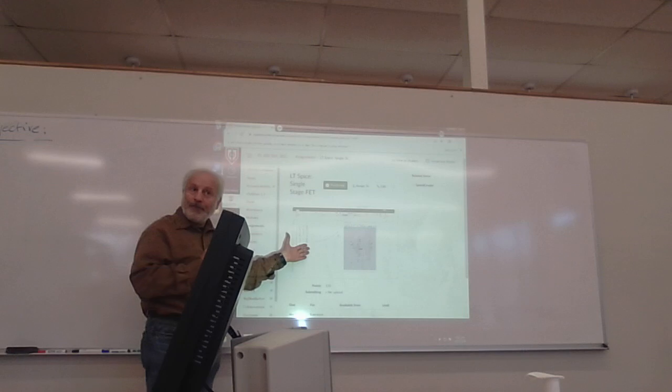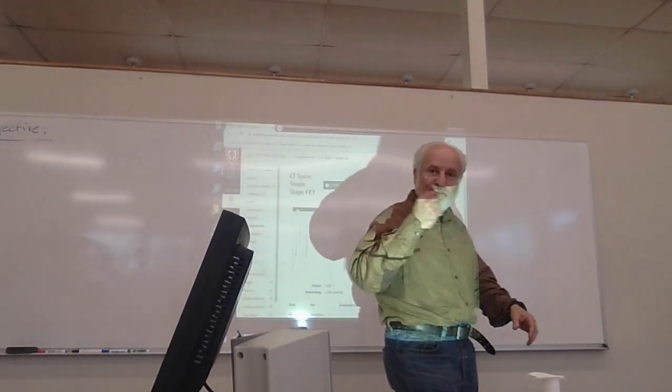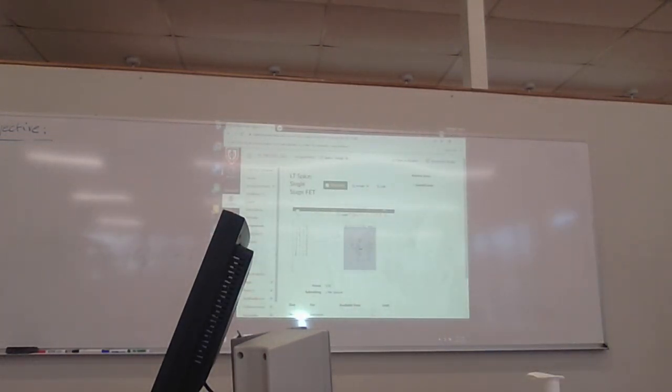Does that make sense? You'll have to pick a few points, see if it fits in the equation of the transconductance. Got it? So you can pick 2 points right off the table, put them in the transconductance formula, and see if they're 0 equals 0. We're good to go. Does that make sense? That's how you prove backwards engineering, right? So if you're given characteristics and already some table data, go backwards.